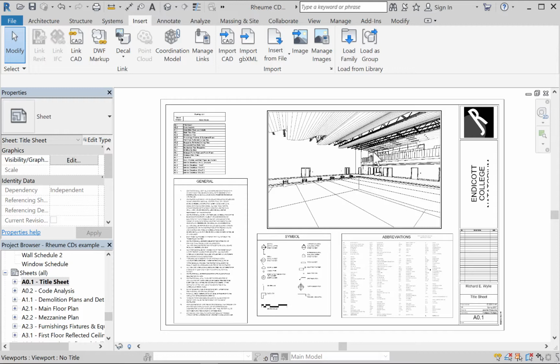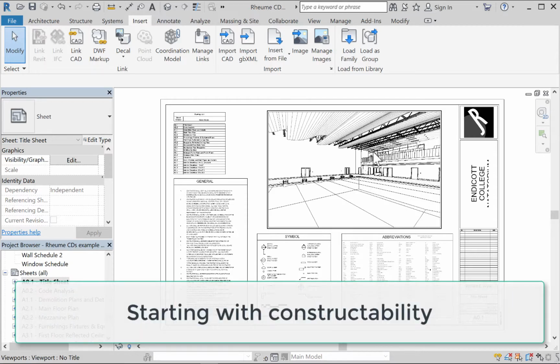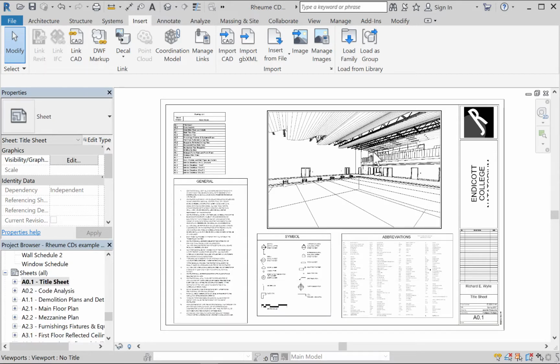So anyway, when you start, the first thing, of course, is go through your schematic design set, address any comments, any obvious errors, things like door clearances, which we will have a little exercise in class. Obvious things, rookie mistakes, like not having doors into rooms. Also, any design features that you wish you had changed when you were presenting it, this would be the time to make that change before you delve into design development drawings.